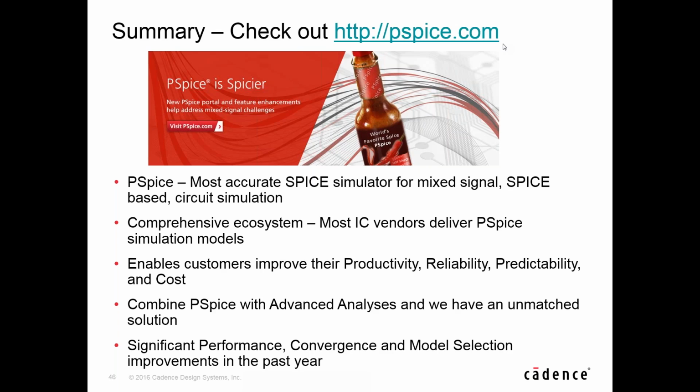Oh, yes, we can do that as well. A lot of our users requested that, so we listened to them. In those modeling apps I was talking about earlier, we have modeling apps for resistors and capacitors and inductors, and some of the parameters in those modeling apps are the parasitics that you just mentioned. So all you need to do is enter the parasitic values in, and those will be built into the model and placed on the schematic.